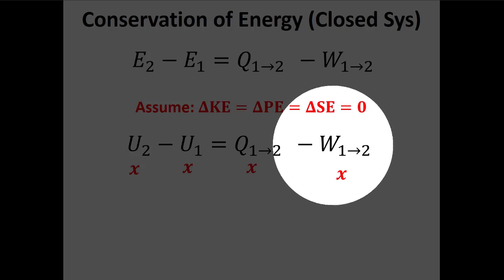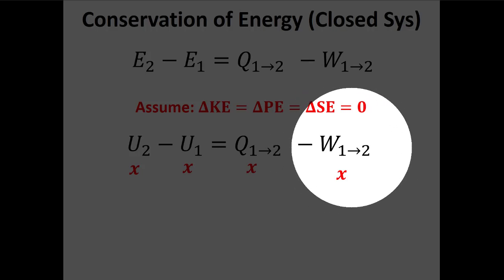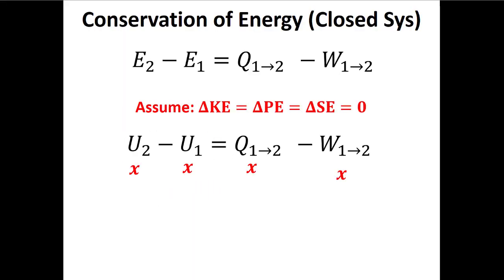So here we got work, I can take the work path first, or I can take delta U first. It doesn't really matter which one you do first. Maybe on an exam problem, just because it makes it easier to grade and it helps lead you through the exam, part A would be find the work and part B would be find the change in internal energy. But if you were just doing this by yourself, you could pick either path. You don't have to walk down the path that the problem is leading you. If you don't remember how to find work, find delta U first.